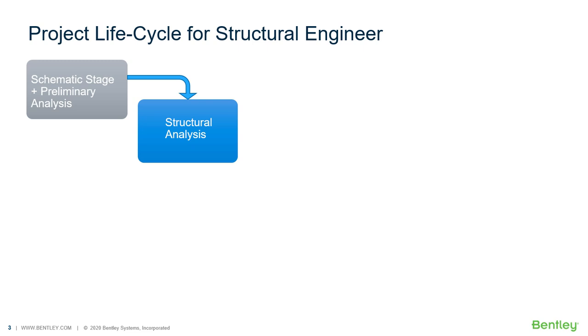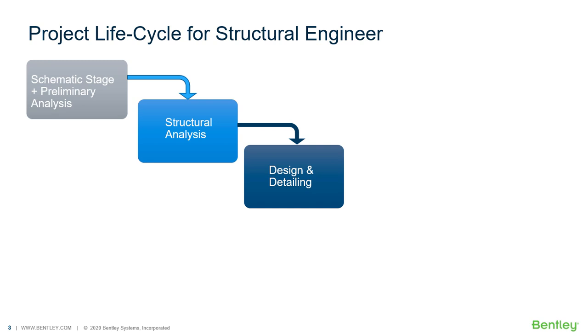Once the analysis is performed, generally engineers will check the stability parts. So whether the deflections are in control, whether the mode shapes are in as expected manner, and all those things. And once they are sure of that, they will generally go for design. During design, the first step is to actually arrive at the area of reinforcement required for various parts. So be it column, be it beams, be it shear walls, be it slabs.